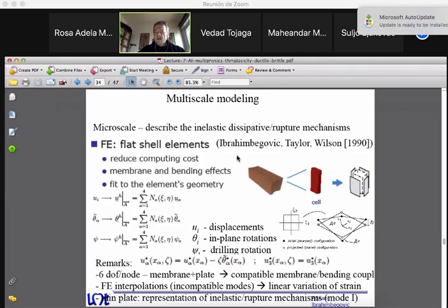Then inside these 4 plates or flat shell elements that are coupled together, you stick in one of these heat radiation elements, which is supposed to simulate what happens in transferring temperature through the empty space. Basically, you have this solution to the heat radiation problem. So the domain becomes rather heterogeneous. You have the membrane and the bending action represented by the shell element, and you have a heat transfer action represented by the solid heat transfer type of elements, all coupled together into a thermomechanical coupling.